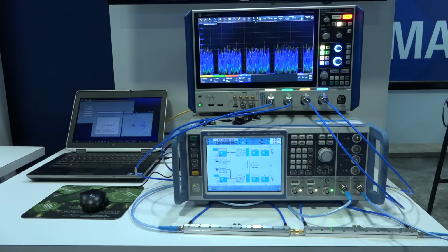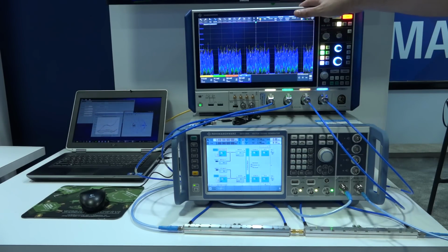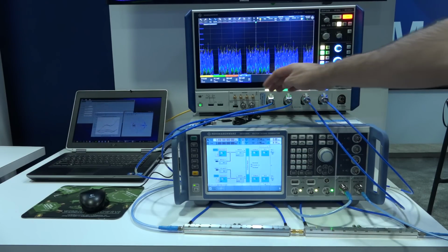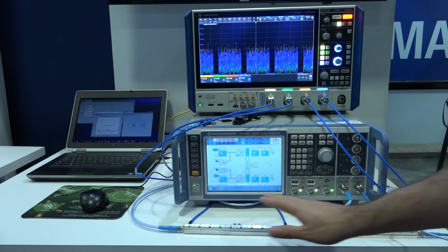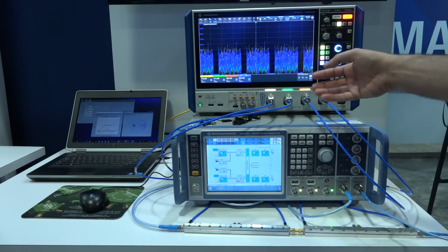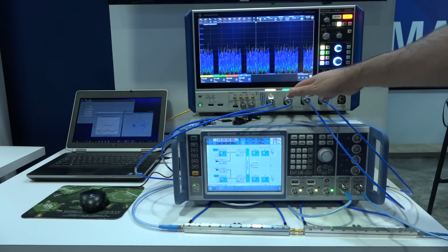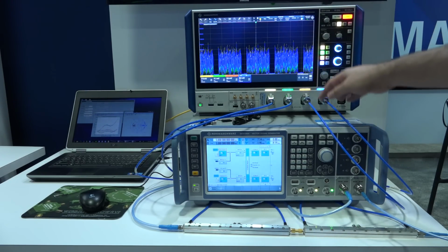Good. And so here's something new. We're using the combination of the SMW200A and the RTP oscilloscope to create an active load pull system. Now, in order to do that, you're going to use all 4 channels of the oscilloscope and the 2 channels of the synthesizer. You would need 2 external couplers, and it allows you to actively generate the signals required to do that load pull. And because you're monitoring all 4 channels at the same time, then you can put it onto software and create your active load pull anywhere on the Smith chart.